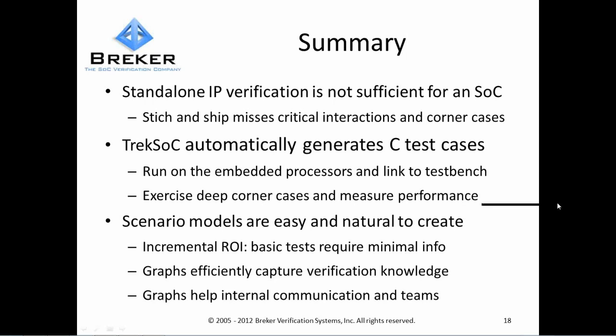We think we're very much following the footsteps of constrained random verification as it has stood for a very long time. And all we're doing is replacing the notion of a CSP constraint solver that's based on rules and numbers with a graph-based constraint solver that's rules on how you traverse a graph. But I still think you're just defining entire input spaces, all possible outcome spaces, and trying to reach them randomly, hitting them randomly.